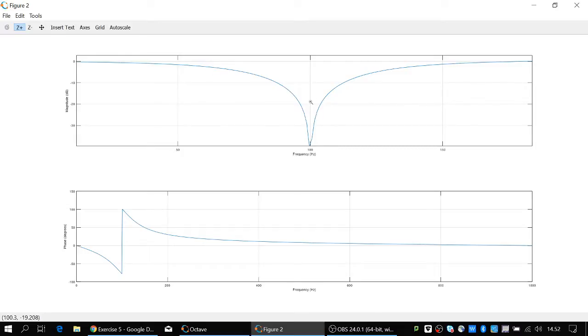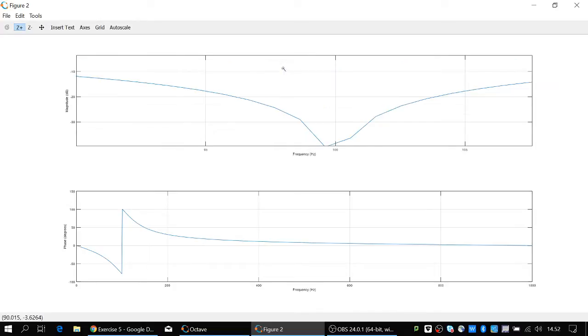The design works, but you also can see, okay, if the line humming was not at 100 Hertz, but a little bit off, say, let me expand that, but, yeah, 5% off, meaning that on a microprocessor you're using the internal oscillator, which usually has a few percent of accuracy.